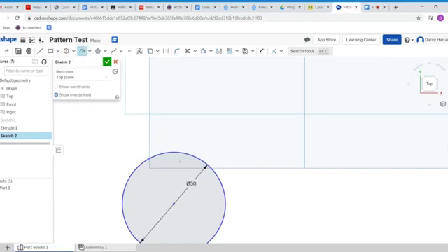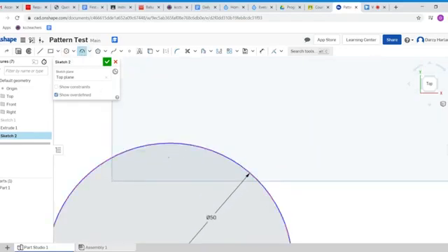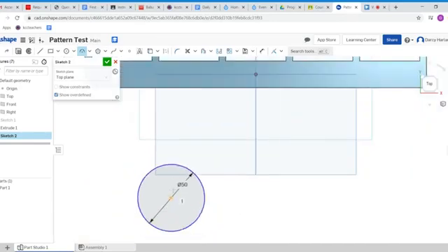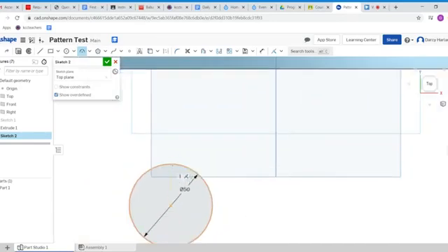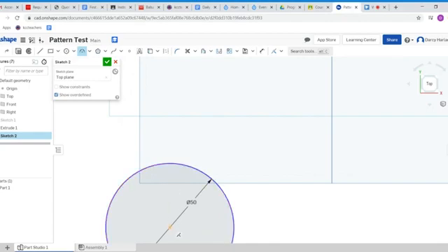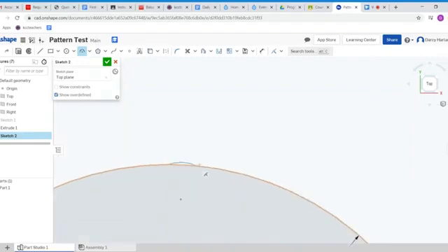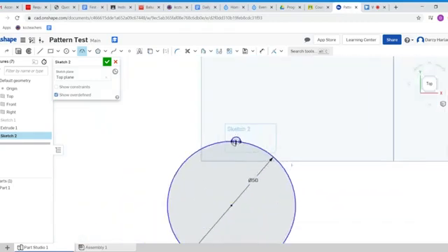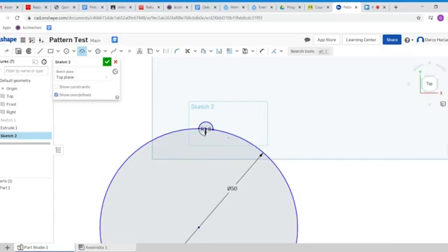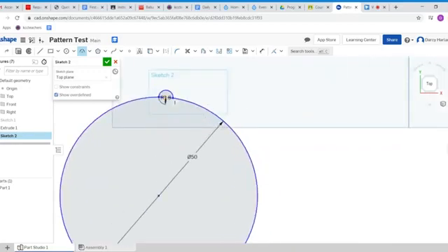Okay. And let's say we wanted to draw a tooth on the top of this circle. I'm going to make sure it goes to the very top from the center there. I'm going to use the center point going out vertically. I'm going to draw 1 point there, 1 point there, and 1 point right on the edge like so. That's 1.8. I'm going to change that so it's exactly 1.8 millimeters. Very radius. It's a radius we're looking at there for an arc. And with this arc, let's say I wanted this arc to go all the way around the circle.